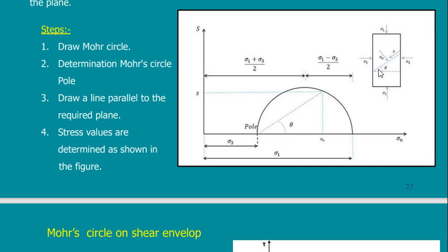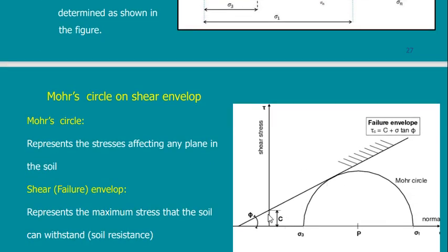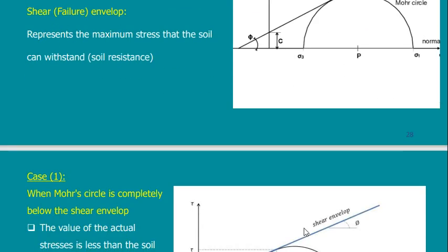So, which one is the surface that will cause failure? Mohr said that the surface that will cause failure is, of course, he made lots of trials till he discovered which point is the plane of failure, this, or this, or this. This we will see in the next slide. You remember our equation that shear strength is c plus sigma tan phi. What he did is that he drew this line and he started with the value of sigma 3. I think it is in the next slide.